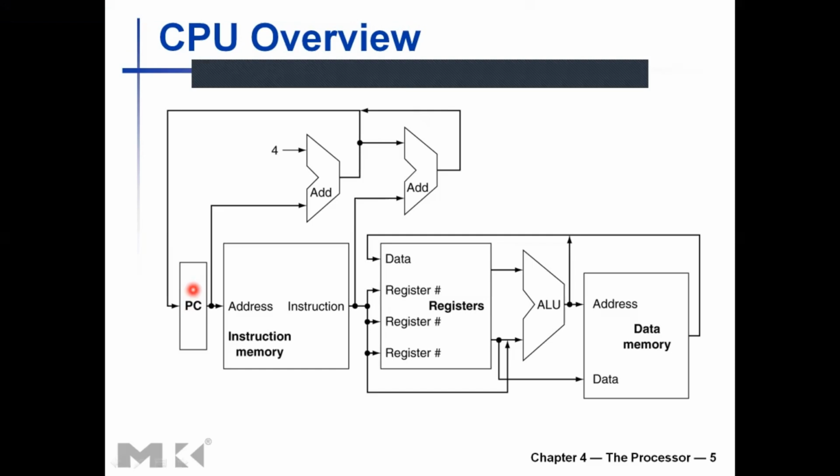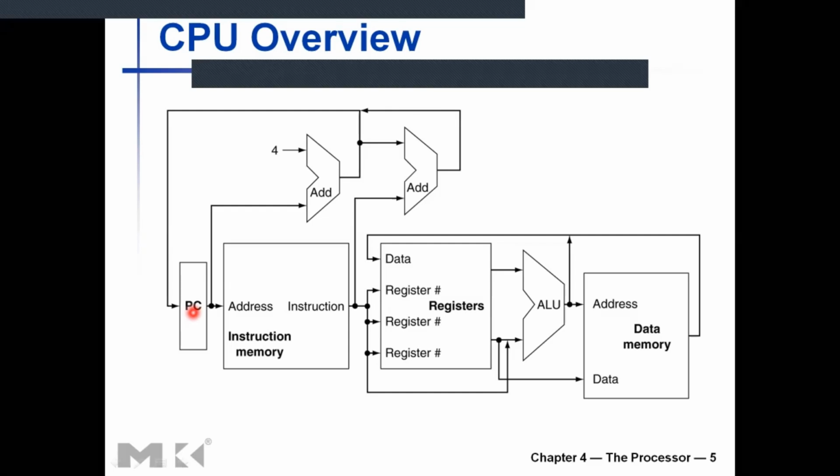Okay, that's good. Right. So the program counter here is used in the instruction fetch mechanism that we discussed in the previous slide. In the instruction fetch mechanism, you go and fetch the instruction from the instruction memory. So based on the program counter, you go to the instruction memory, provide the program counter's address into the instruction memory, and retrieve the appropriate instruction from that address, bring it into the CPU, right? So at this point here, the instruction is inside the CPU.